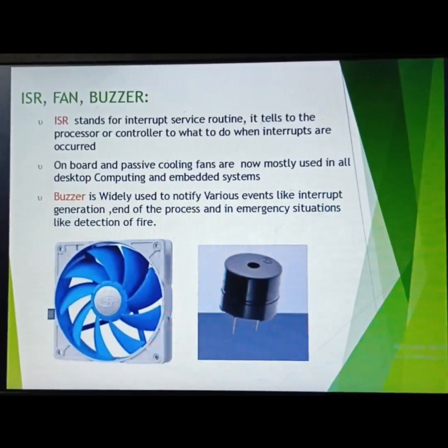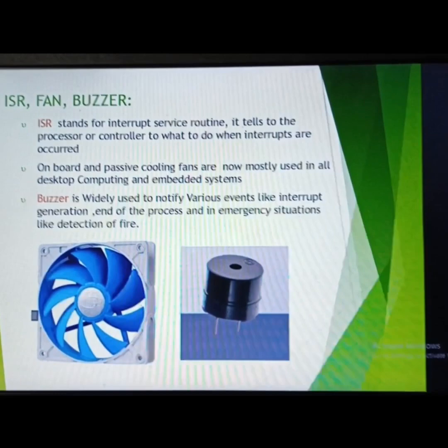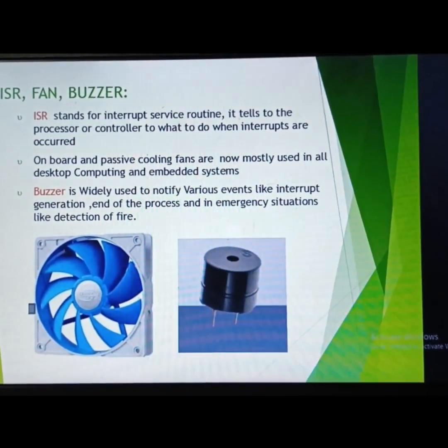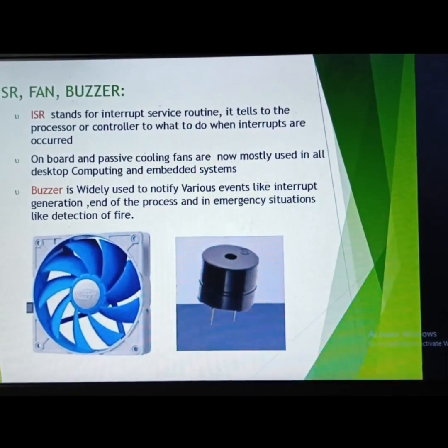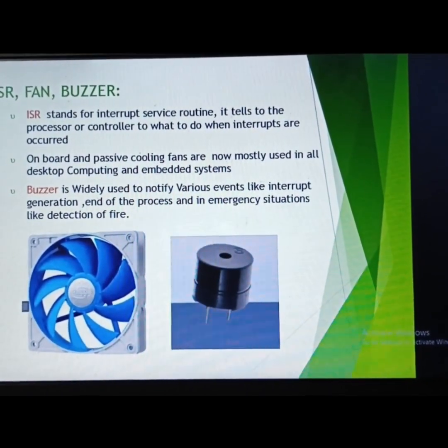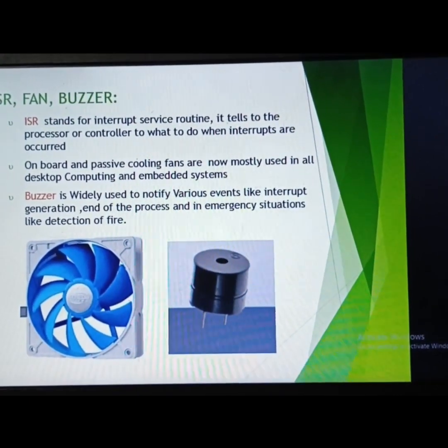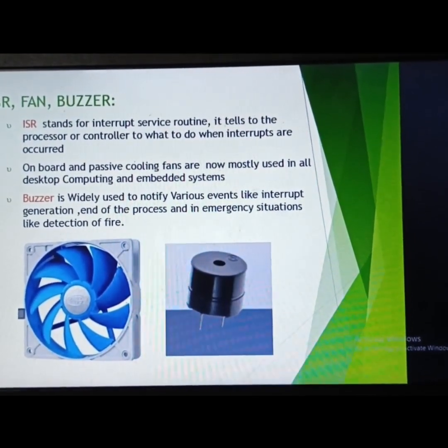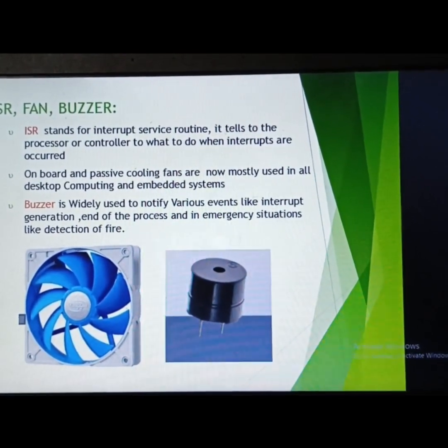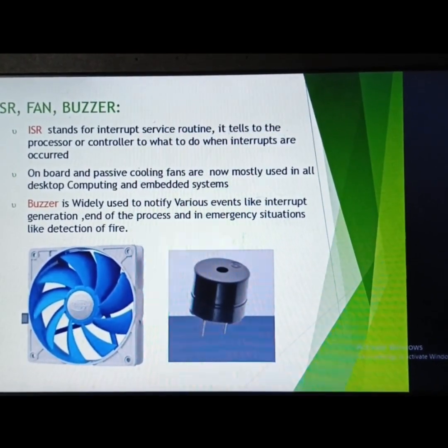Coming to the next components: ISR, fan and buzzer. ISR stands for interrupt service routine. It tells the processor or controller what to do when interrupts occur. Interrupts can be because of hardware or software changes in the program. In our project, we require a timer to create an interrupt once the washing process is over. For this, I have used timer 2 of the PIC16F877A microcontroller.